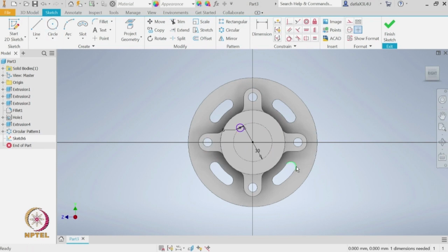Now, we need to specify that it is at an angle of 45. So, the location needs to be precise. For that, let us use this dimension, select the center of the hole, origin and okay, we notice that we do not have a line. So, first let us use the project geometry to create a point. Now, let us again go back to the dimension, let us specify the angle using the 3-point method, first on the center of the hole, origin, and this point we have on the horizontal axis. So, this angle we said is 45.